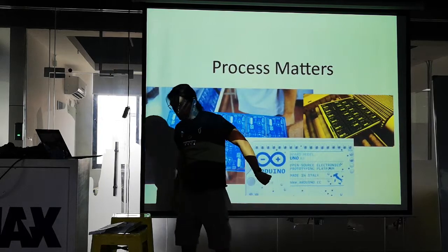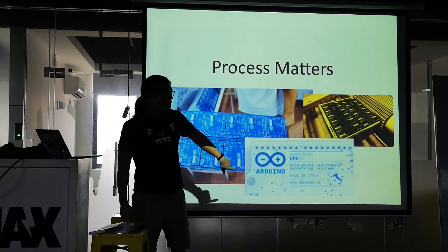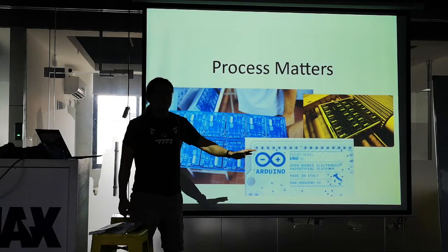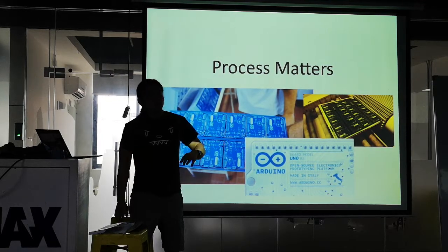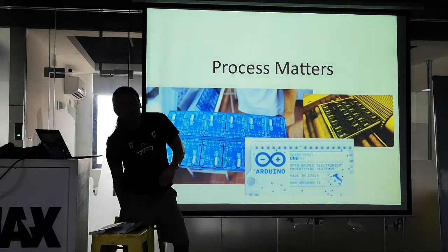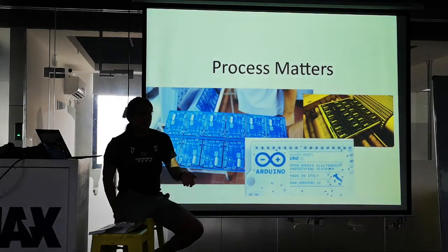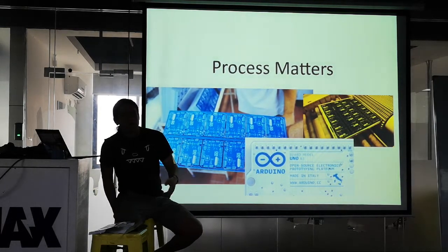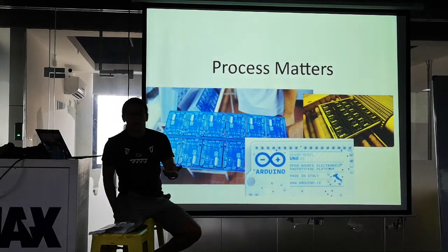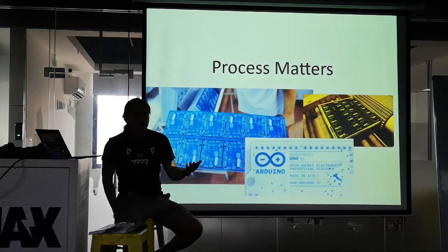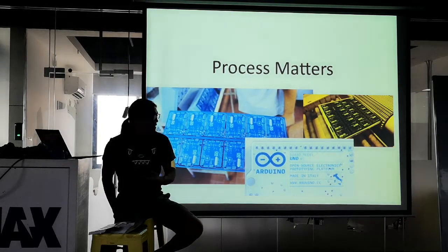It turns out the way they did this is it's not silk screen. They put two layers of solder mask down, first the blue one and then the white one. I didn't even know this was a thing, that they put multiple layers of solder mask on a PCB, until I visited a PCB shop. It's just a film they put down. It's actually pretty cheap and they put more and more layers on. Some people have gone nuts and put like 8 layers of solder mask on to build full color graphics on the back of their PCB and then shipped it to people, right?